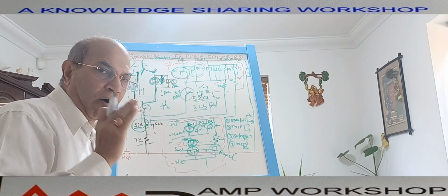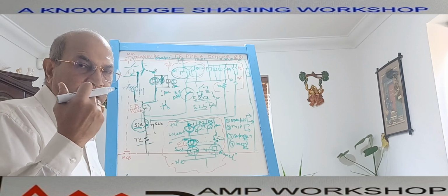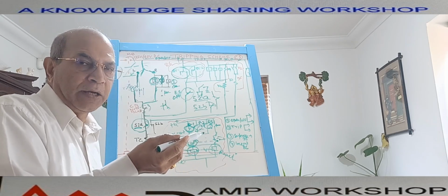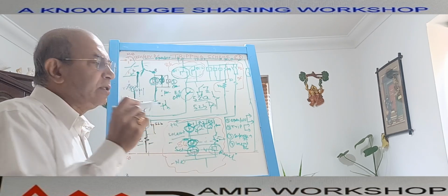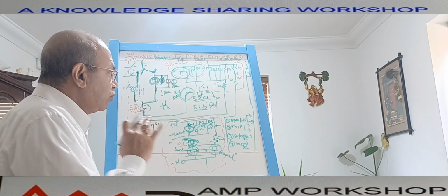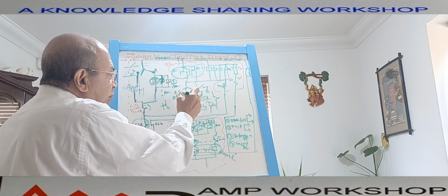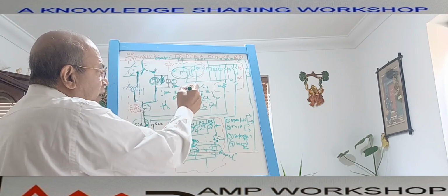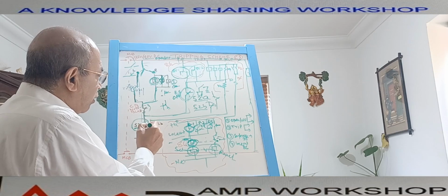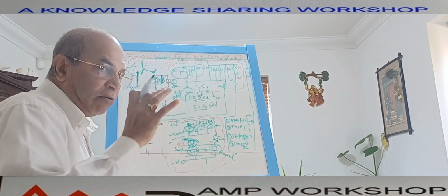This earth switch is not on when the earth switch is open. If somebody puts the earth switch handle to open it or to make it earth, then that will be dangerous. So that's why we put this interlock, that the earth switch is in off condition. The earth switch rod has not been inserted. The moment you insert it, it becomes open, so even with a fault it will not trip. That is a danger. That's why we put an NC condition, and then it comes to the same logic. The breaker is already closed, so it will go to the tripping coil. So this is the fault trip of this particular circuit.